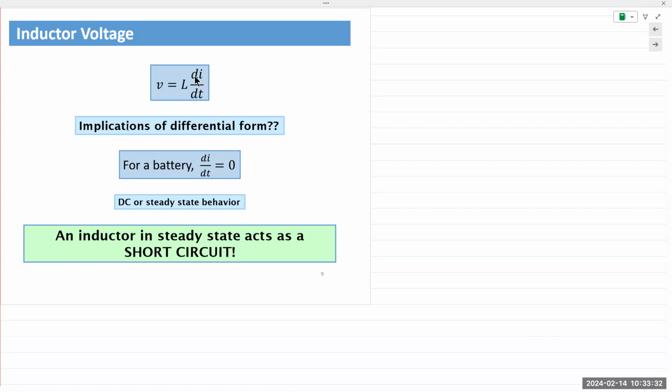If I is a constant, meaning a DC current is applied to an inductor, once it reaches steady state, meaning it reaches that level of current that is being applied, from that point on, the voltage is equal to 0. So if we had a meter and we connected it across the inductor, depending on how fast or slow the circuit is, or how big the inductor is, we would see a voltage until the point where the inductor reaches full charge. And once it reaches full charge, that voltage would go to 0. Make sense?